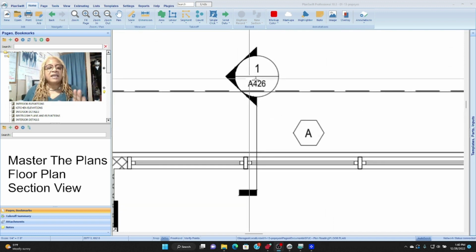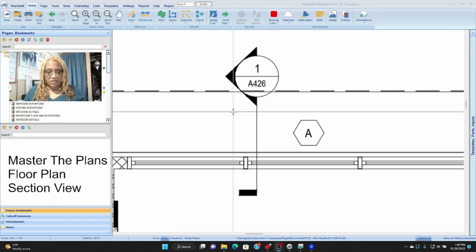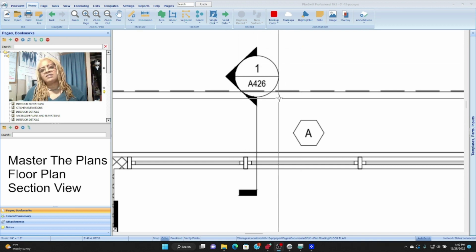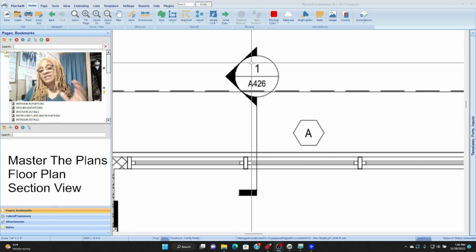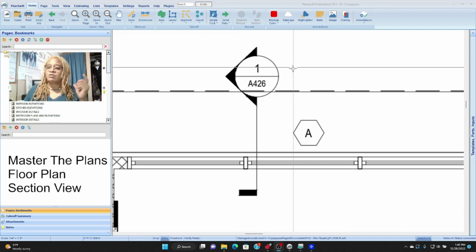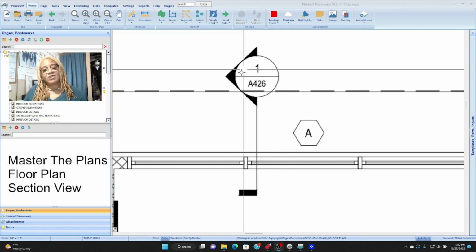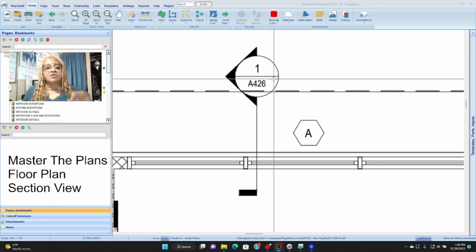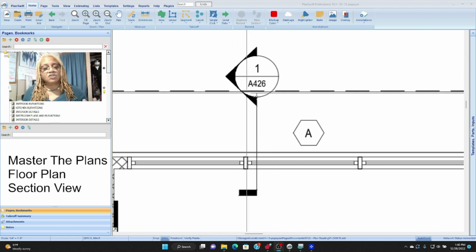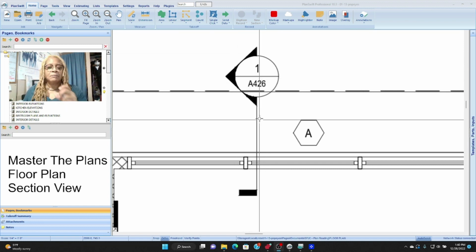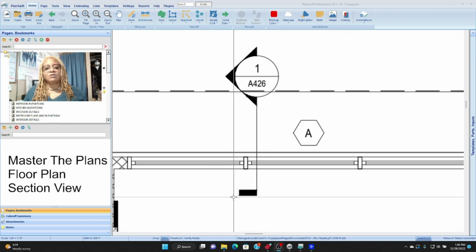And so if I go to, and this is how you read it, right? So the section view marker looks like a detail marker, but the detail marker doesn't have this little sideways hat. Okay, so that is the difference. So the section view marker is very unique. The circle, the little hat, a leg, and this little extension, I call it a foot.